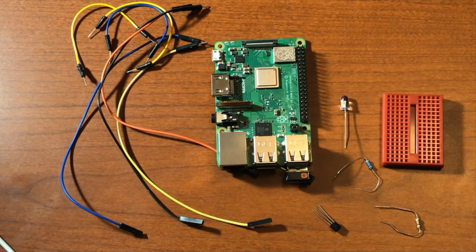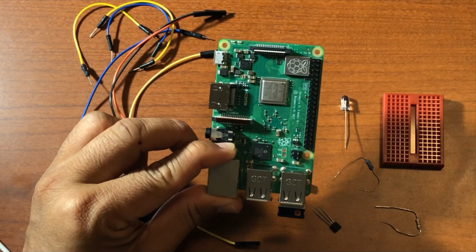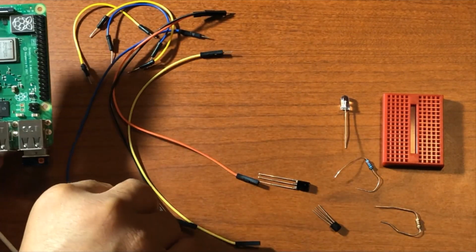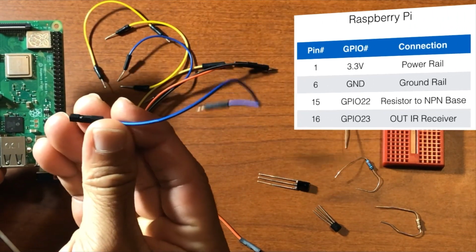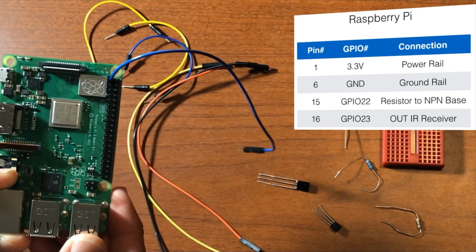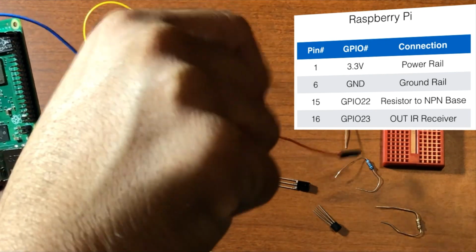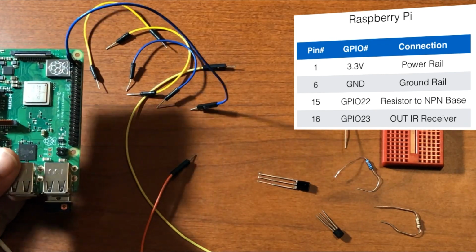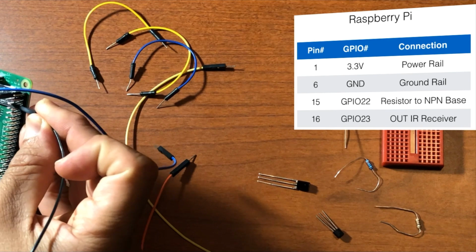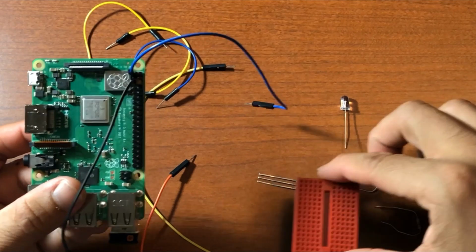Okay, let's get started wiring up our circuit. Here we have the Raspberry Pi, and let's first connect the 3.3 volt and ground pins. So I'm going to take one of these female to male connectors here, and this pin on the left here is our 3.3 volt pin, and for our ground pin we're going to use the third pin down on the right. All right, so we're going to count down 1, 2, 3. This is going to be our ground connection. So I'm going to connect that to the breadboard.